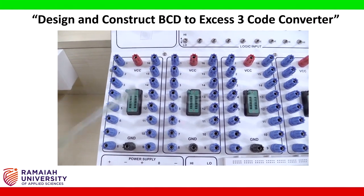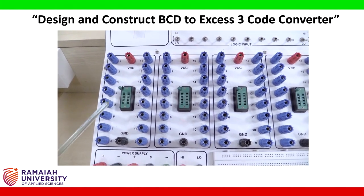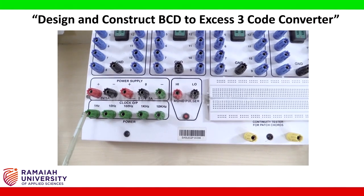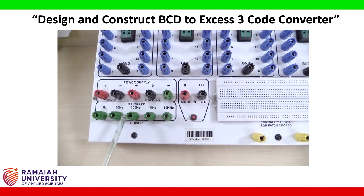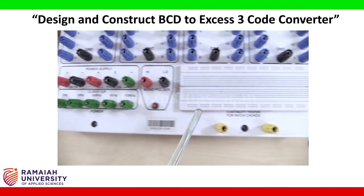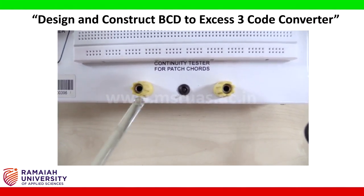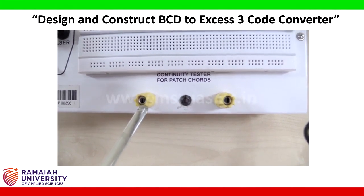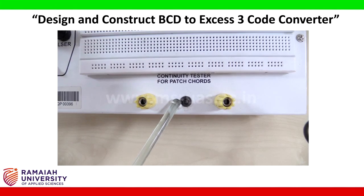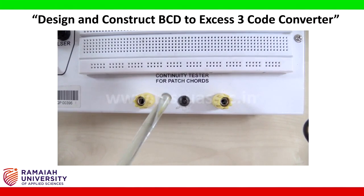So VCC and ground are used to give the power supply to the IC connected here, and at the bottom you can see there are the clock signals of various frequency: 1 Hz, 10 Hz, 100 Hz, 1 kHz and 10 kilohertz. And at the right side you can see there are two yellow color knobs which are used to check the conductivity of the patch cords. So if we connect the patch cord here, and you can see if the LED bulb is on and if the beep noise is coming, that means the patch cord is working properly, otherwise the patch cord has some problem.